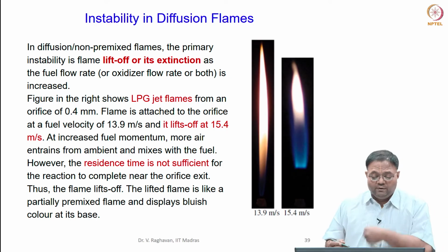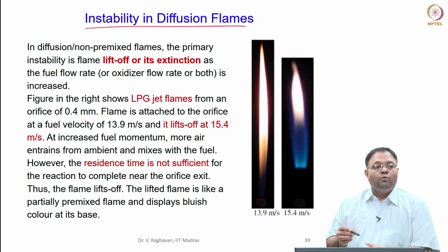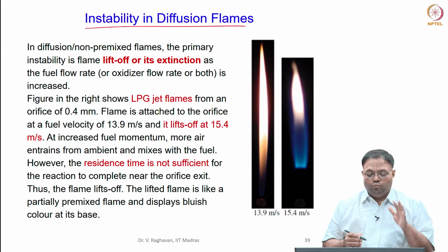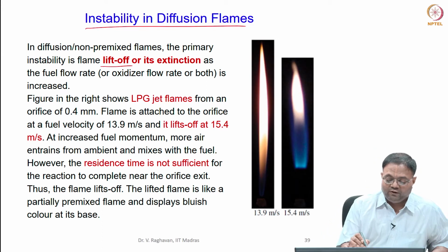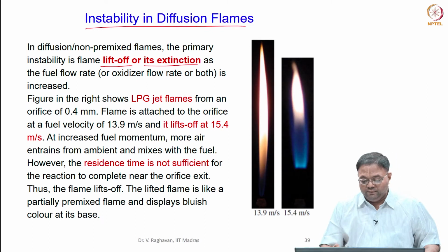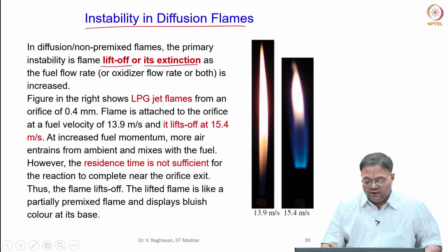Now, instability in diffusion flames. What are the possible instabilities we have in diffusion flames? There is only one, that is lift off and subsequent extinction. You can see that again I am giving the example of the LPG jet flame.